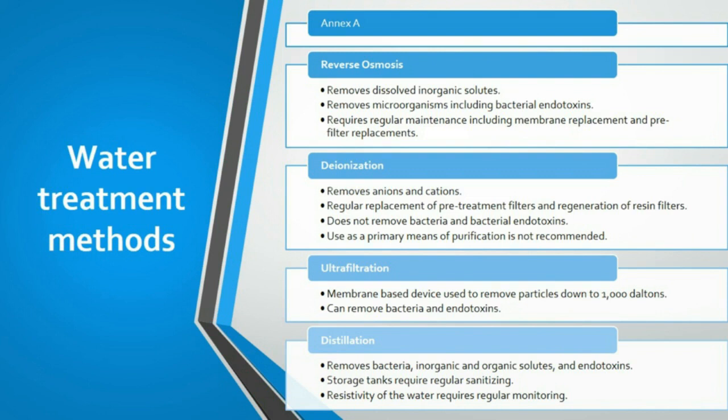Ultrafiltration is a membrane-based device used to remove particles down to 1,000 Daltons, and that can remove bacteria and bacterial endotoxins. And then distillation. When you have distilled water, that removes bacteria, inorganic and organic solutes, and endotoxins. Storage tanks are required, and they require regular sanitization. If you want it to stay distilled, that's something you have to work on with the storage tank. And resistivity of water requires regular monitoring.